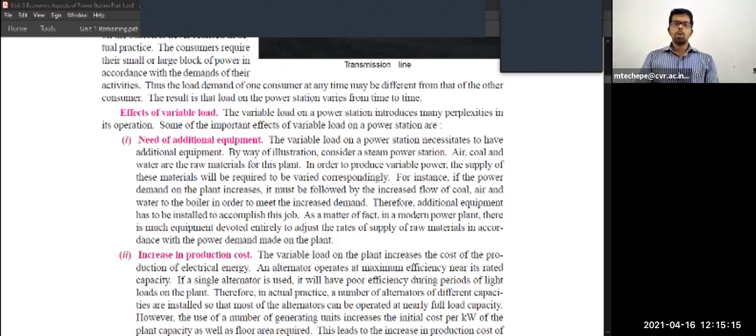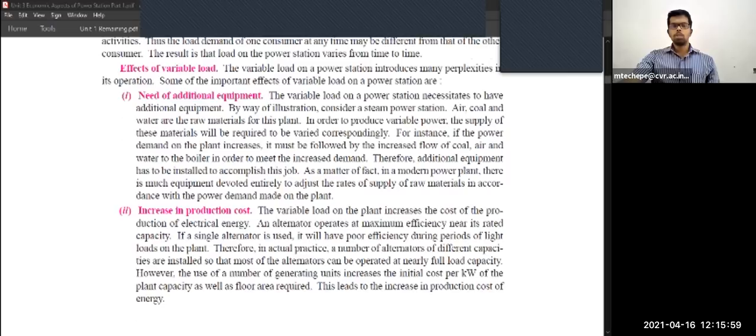And in old plants, the backup transformers and backup generators, reserve generators might be few. Now in modern power plants and modern substations, the backup generators and reserve generators will be there, then backup equipment might be there. So if one transformer fails or one feeder fails, you can switch over. You can change that bus to that particular feeder, so you can switch over the transformer rating or switch over the feeders very easily.